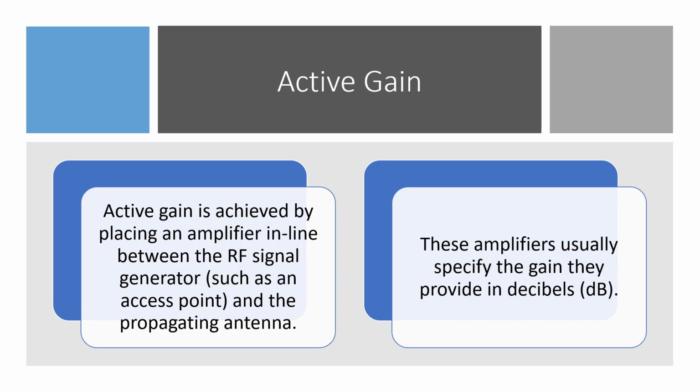The main job is that the RF amplifier receives the incoming signal and boosts it by adding a gain, which is normally specified in dB, decibels. It will say that it increases by 10 dB, or 3 dB, or 5 dB. So if you look into any signal booster or amplifier, they will have the gain given in dB.